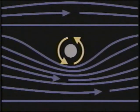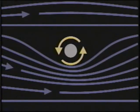Because the conductor's flux lines are circular, they interact with the magnetic flux lines in opposite directions on either side of the conductor. On one side, with both sets of flux lines traveling in the same direction, they become tightly spaced and work together to create a stronger magnetic field. On the opposite side, where the two sets of flux lines run in opposing directions, they become more widely spaced and form a weaker magnetic field.